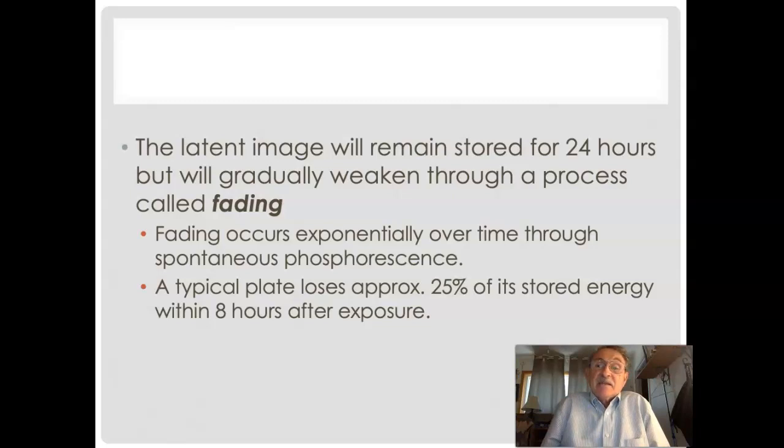Okay? And it is therefore important that we process a CR plate as soon as possible after exposure. Here's the reason why. A typical plate loses approximately 25% of its stored energy within 8 hours after exposure. Okay, 25% within 8 hours.